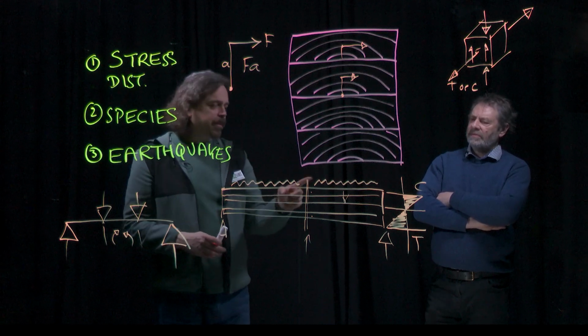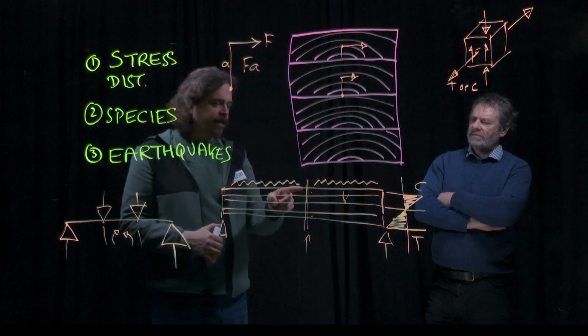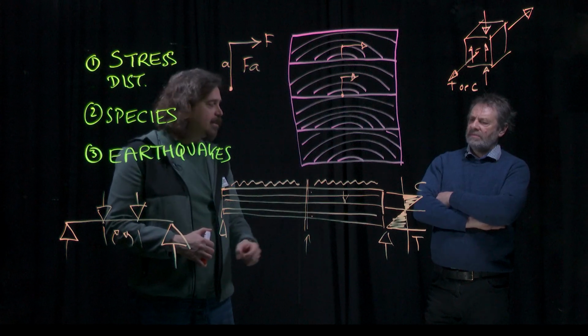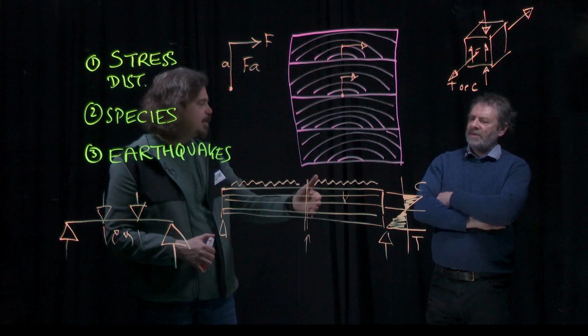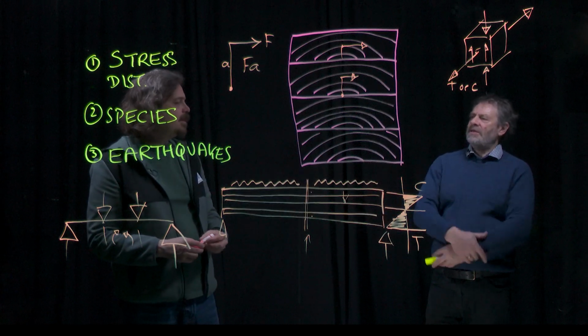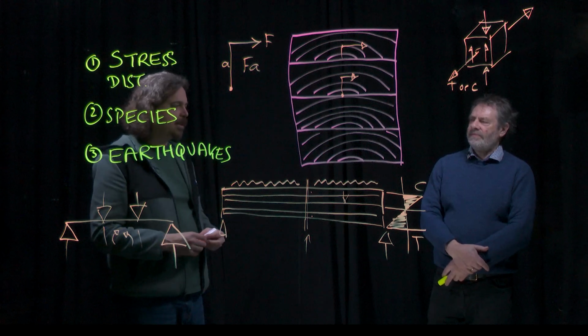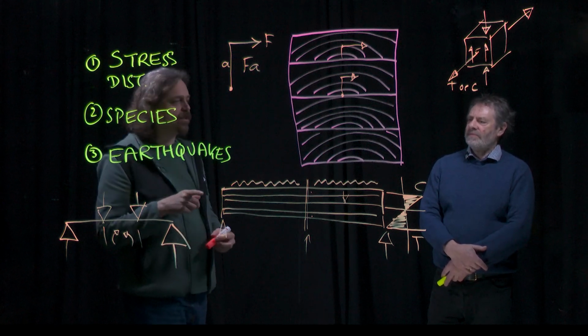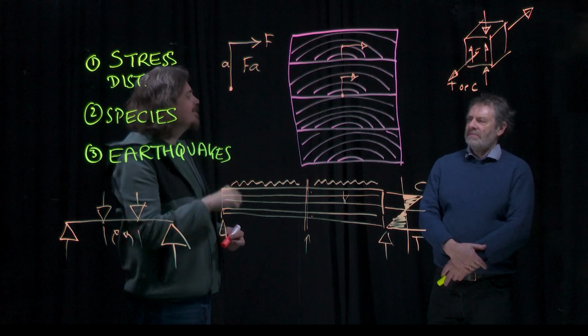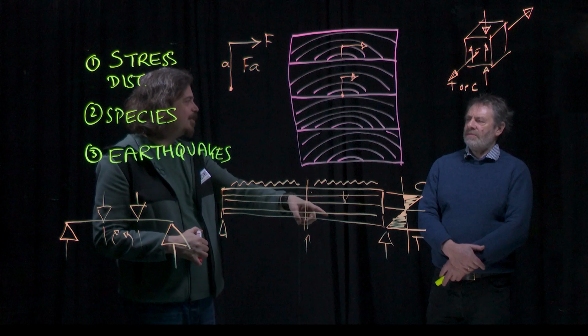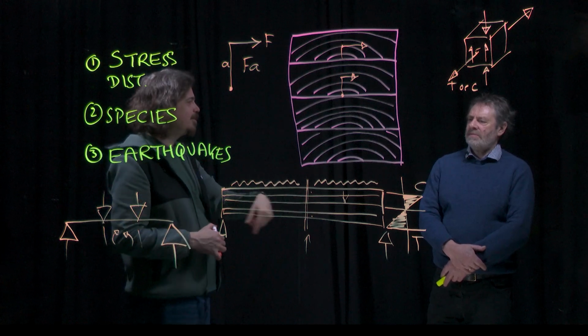But what would cause a difference is if you had different stiffnesses of the lamellas. Because it's wood, each piece of timber is going to be kind of different, randomised, isn't it? It is for what's called homogeneous glulam, where all of the pieces are the same grade, so we're assuming that they're all randomly equivalent.